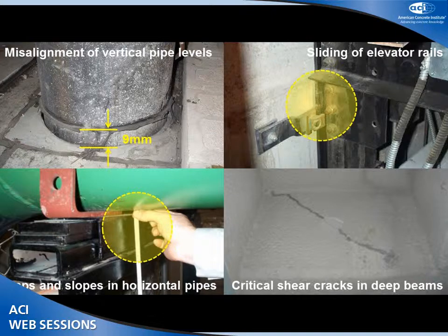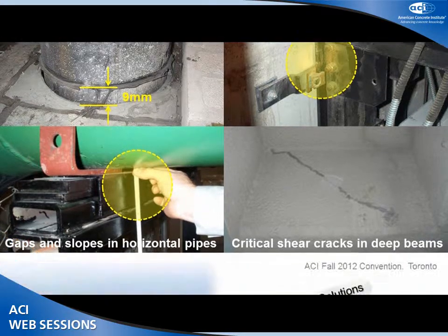Building components attached to the structure, such as pipes and elevator rails, don't want to move. However, as you saw in previous slides, structures move in many cases. And the structure itself doesn't move equally, so that at some points, a stress develops which was not estimated in the usual structural analysis.